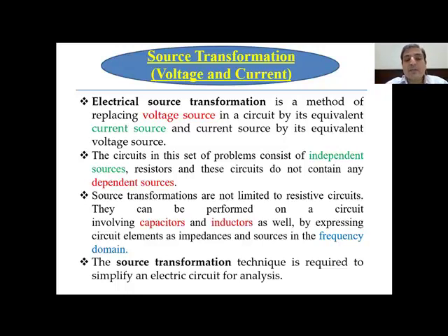In case of the voltage source, generally we have an internal resistance connected in series with the voltage source. Similarly, for the current source, if it is a practical one, the internal resistance is connected in parallel with the current source. And I told in that class also that both of the circuits, voltage source with resistance and current source with resistance, can be interchanged, converted or transformed to each other by their equivalent one.